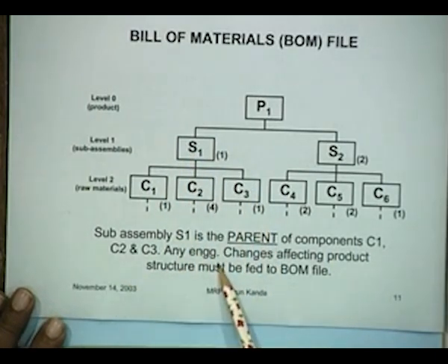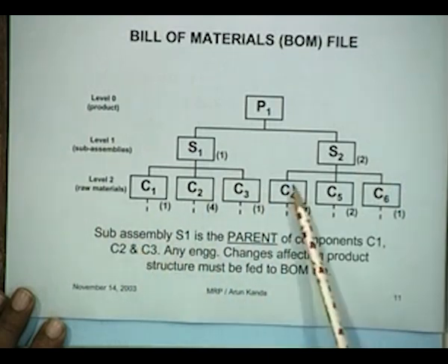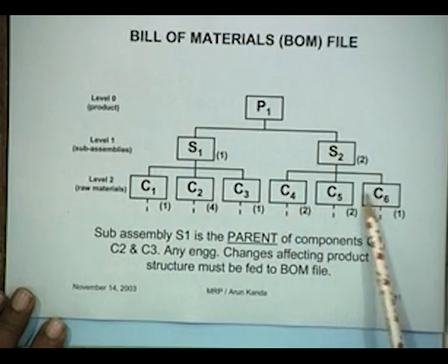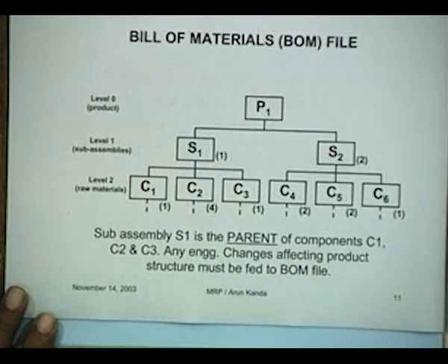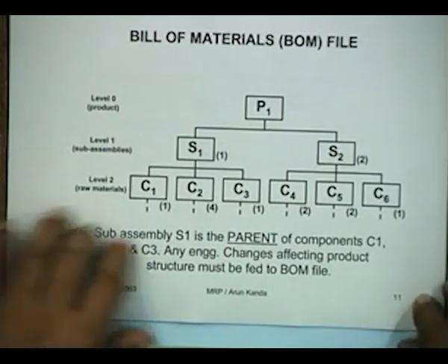And any engineering changes affecting the product structure must be fed to the BOM file. That means if you are changing the design, what does it mean? You are either eliminating this component or making a different component or something. So these changes in the design will have to be reflected in the BOM file that you have with you. Okay.